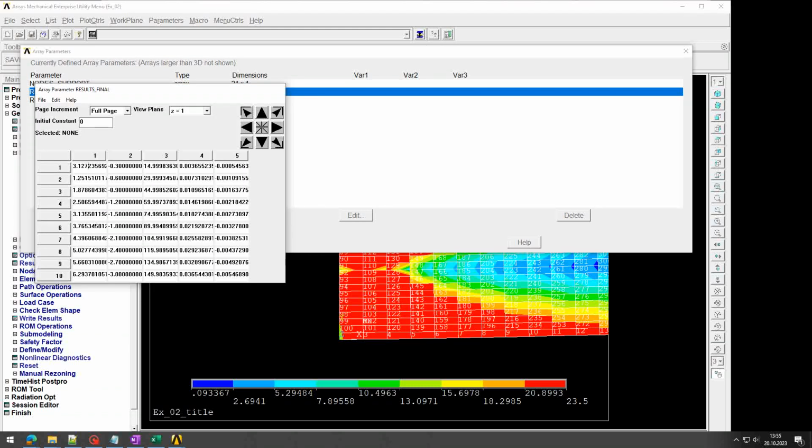Force in X, which is almost 0. I mean, it's not exactly 0 because of the numerical errors. Then we have the force in direction Y. We can scroll down, and you can see that in step 86 the force is around 25 kilonewton, something that we would expect.